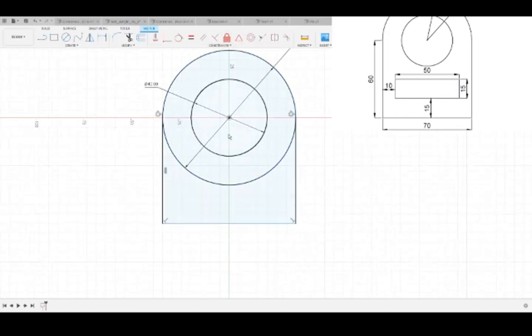You have fix/unfix, which is one that you tend to not want to use because utilizing fix and unfix has a tendency to over-constrain and break sketches, because ideally they should all be constrained relative to a single reference. If you're locking one in space, then that tends to put 2 different fixture points that could otherwise break a sketch. So ideally, you don't always want to use that. There's midpoint, which sets something relative to the midpoint. You can't put points in this, which is something you could do in SolidWorks. That basically defines if you have a sketch endpoint, for example, or better yet, I can actually show this with a construction line.